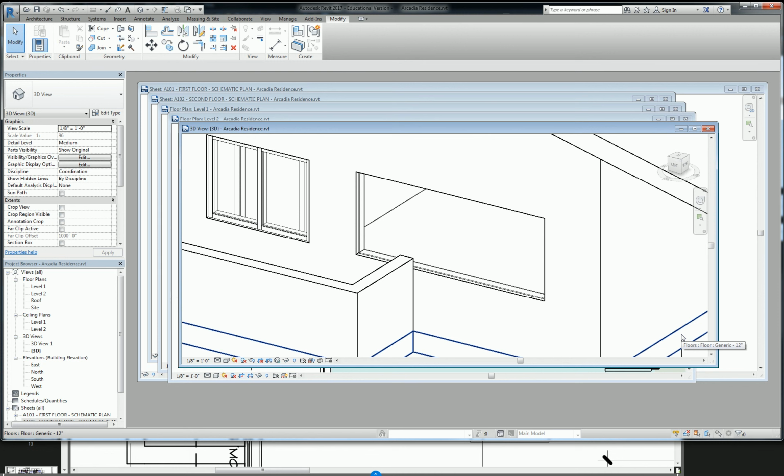Okay, so the difference between storefront and curtain wall is that storefront gets modeled like a predetermined, evenly spaced mullion system, and it just goes in really easy and fits fine. The curtain wall, you have to custom place every single one of your mullions. Okay, and I'll show you all the details for how to do that and how to make it look like what we need. But before we do that, I just wanted to show you everything that we're going to work with. So what questions do you have about this?